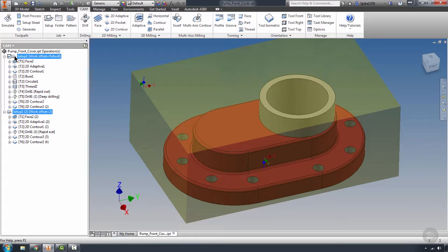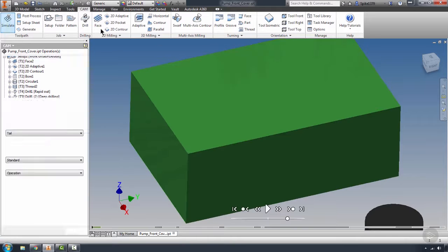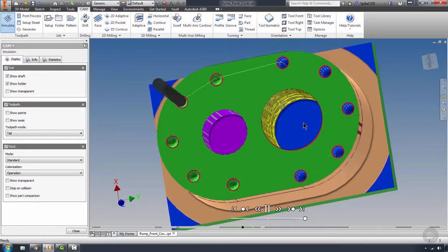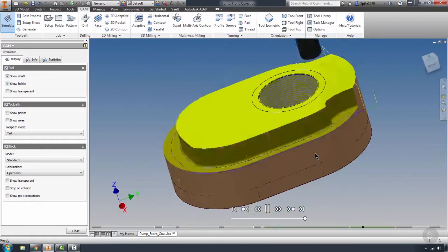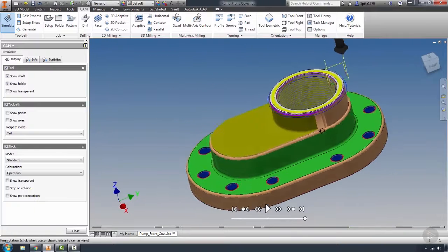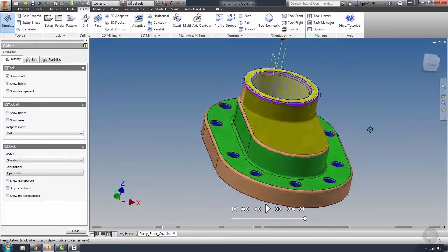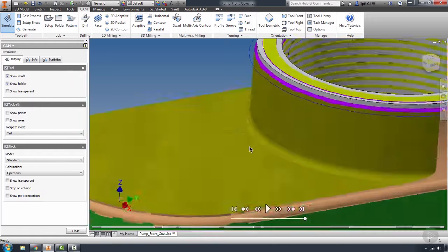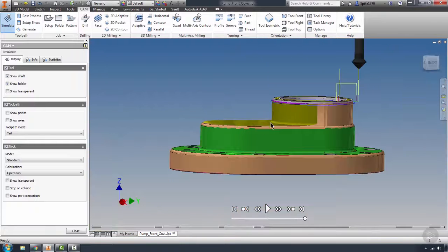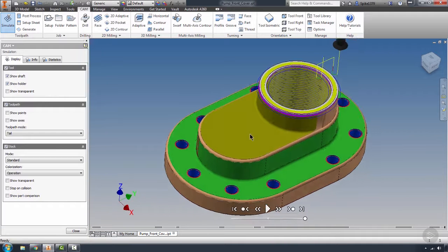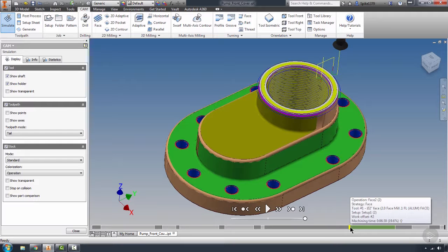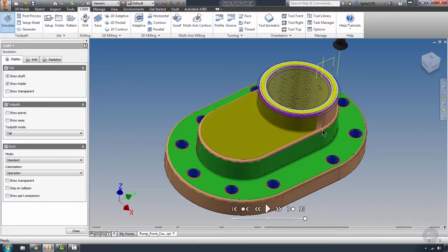So what I can do to take care of that is one of two things. I can simulate both operations at the same time. There's OP1 once again. We're just machining the whole thing. And then it's going to start machining OP2. Okay, so all of that went away because now it's using the proper cutters. It's doing what it needs to do, with the exception of the fact that I forgot a toolpath. Now, the two things here that I see. I got rid of all the problems by adding these operations together, but I've left material on.